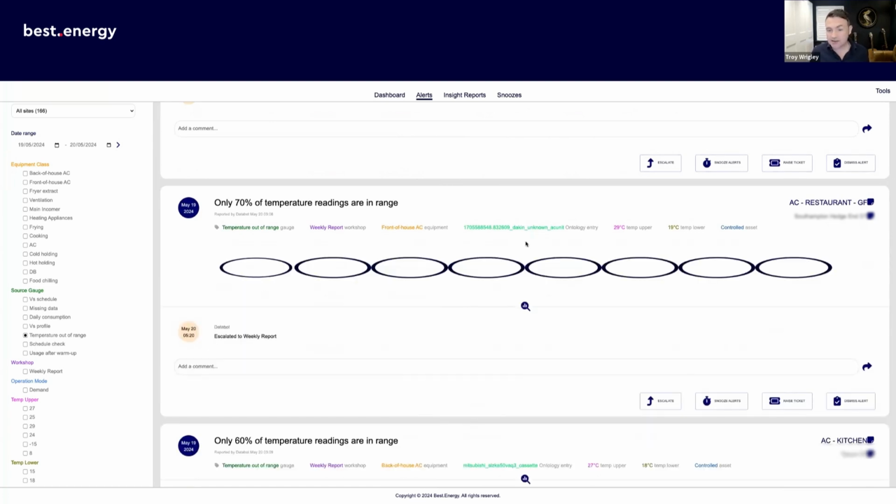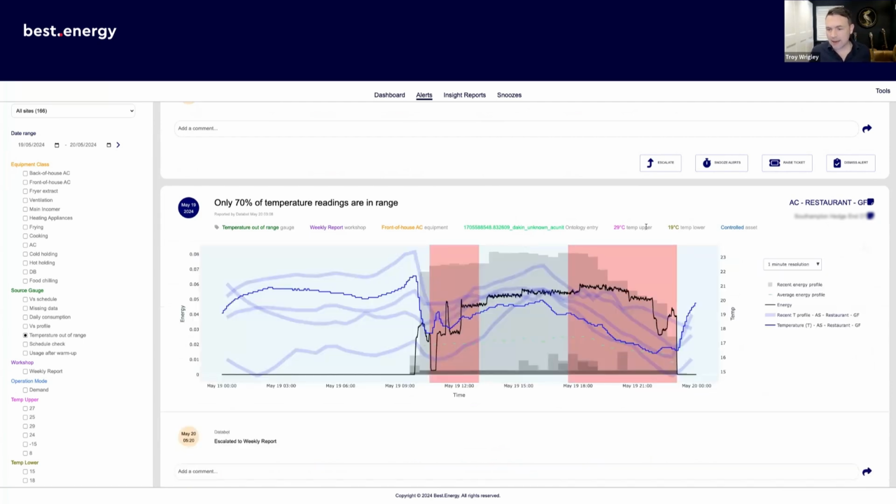So this is where the clients are sitting. So that matters to the client in particular, how their customers feel. And they've set a temperature window of between 19 and 29 degrees. And what we can see here is the temperature is not within the operating parameter. In fact, in this instance, it's dropping below the requirement. So they're overcooling this particular facility.